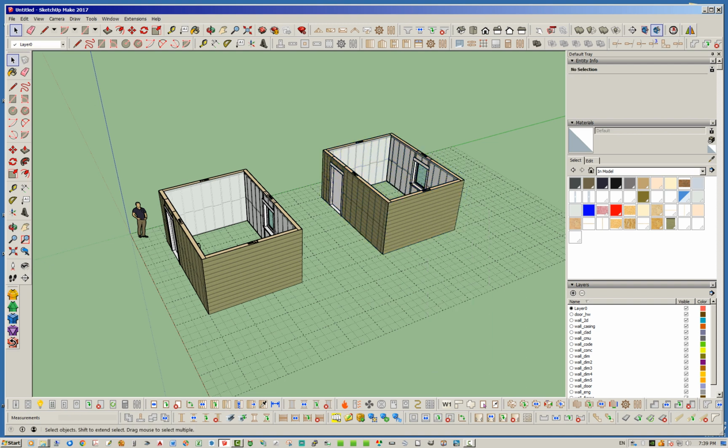It'll regen whatever you've selected. And what will happen is it will break the shared definition for each wall, as well as assign a unique instance name to each one. And that of course is only for the regen feature. So once you copy the walls, you do need to regen those walls. Otherwise you will not be able to edit them or make any other modifications. And if you do make modifications, you will instantly see that one of the walls will disappear.